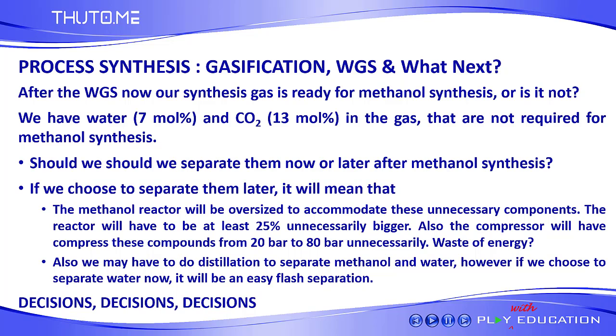So all these decisions, you need to think about them. So I would say my decision here would be to avoid distillation downstream. I need to remove the water. Separation of these gases and water will be just cooling down to a lower temperature where water will condense, and then I'll separate the water.